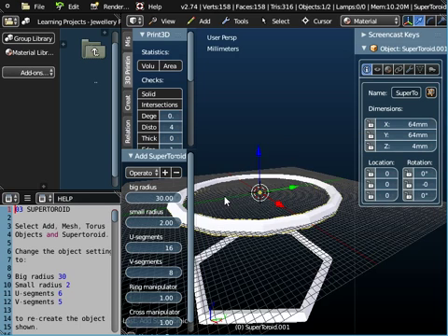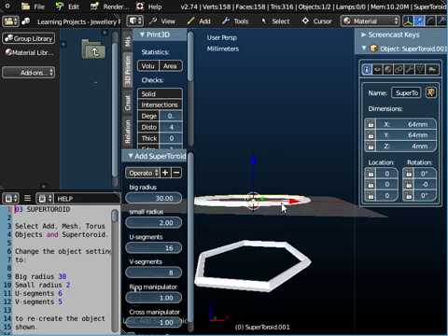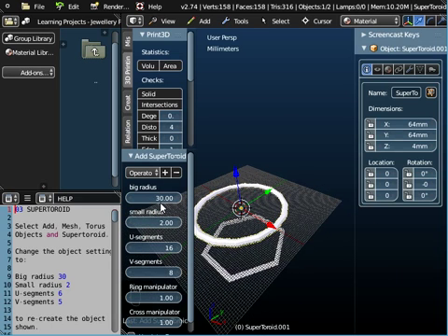The 64 millimeters is made up of 30 millimeters to the inside, another 2 millimeters to the outside, so that's 32 millimeters. And on the other side, another 30 millimeters to there, and another 2 to there. So that gives us an external dimension of 64, but the 30 tells us it's an internal radius of 30.